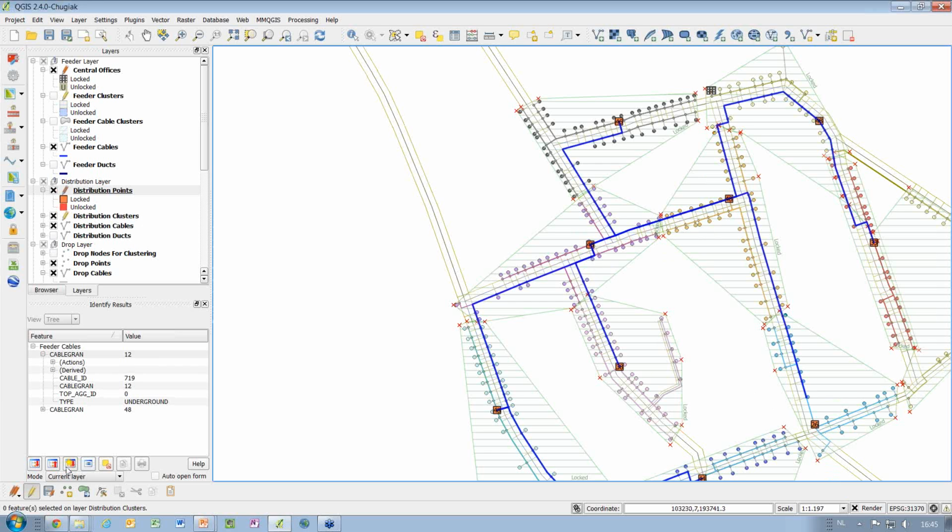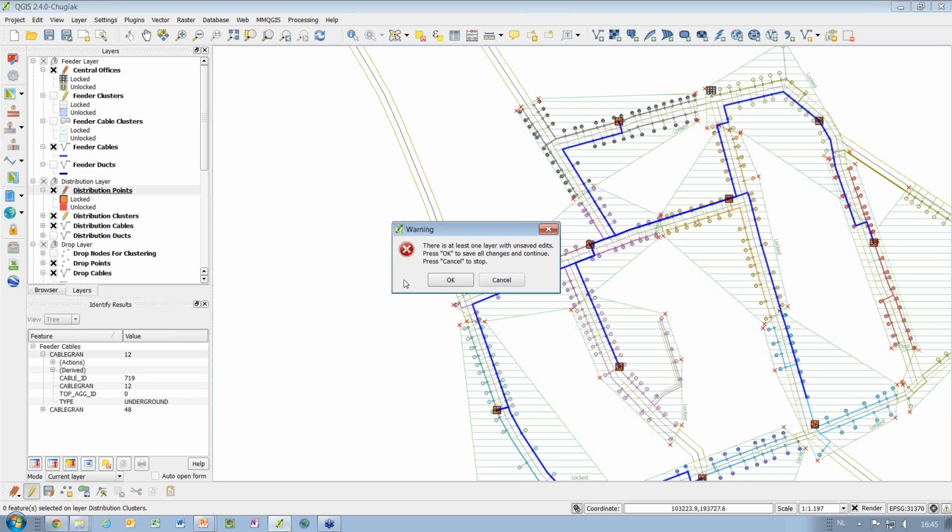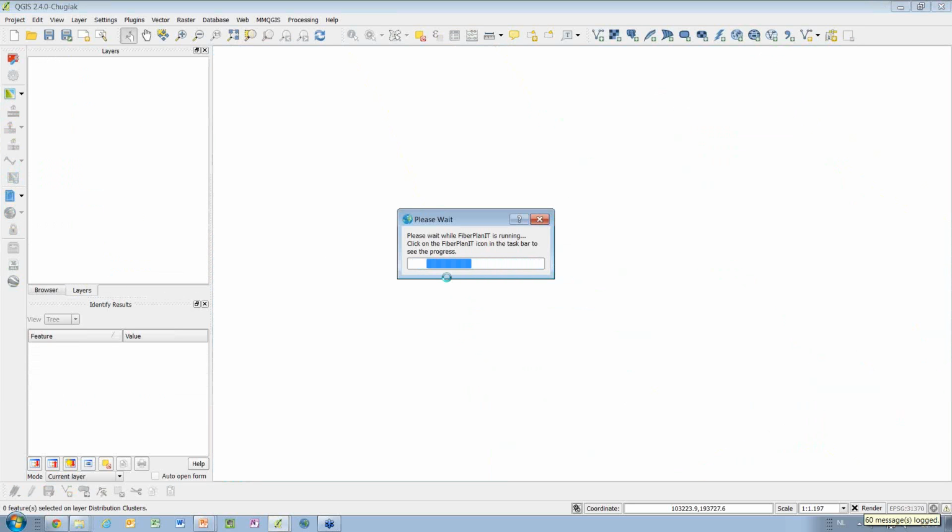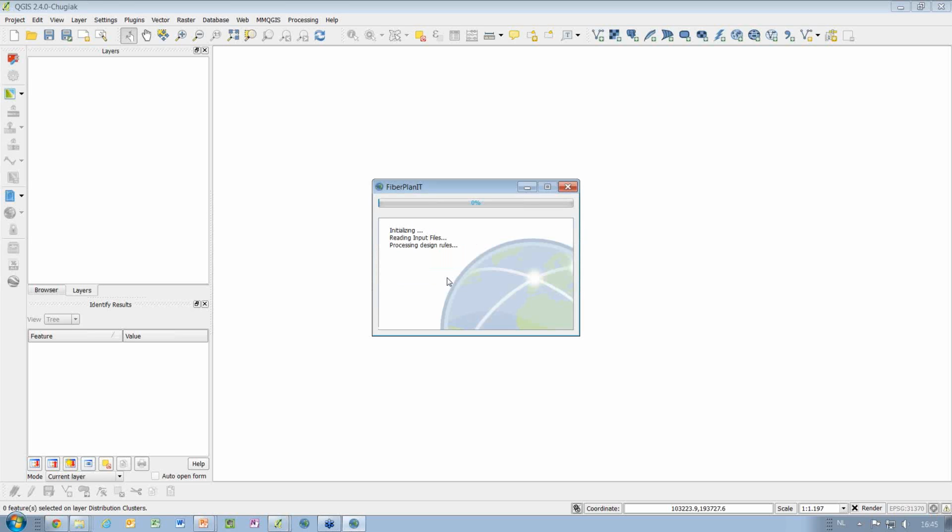So making such changes is very easy, and we are now imposing these different locations, and then we can launch a new calculation, saving our changes, and we will see, after recalculating this area, how the network design is optimized again, given these new locations. Everything is recalculated, so we have no errors, there are no fibers missing, and the cable routes are re-optimized given this new input.